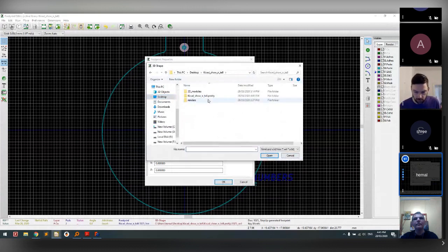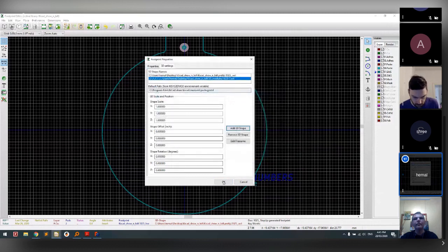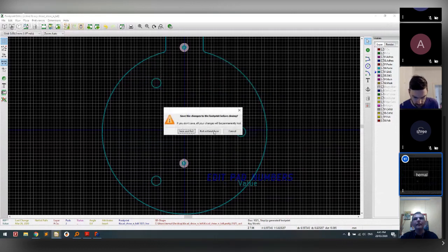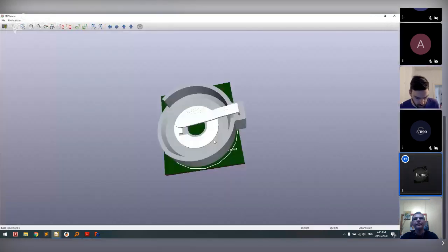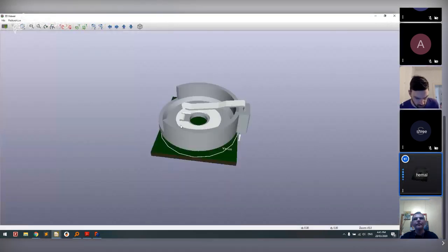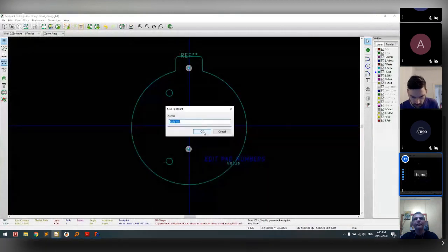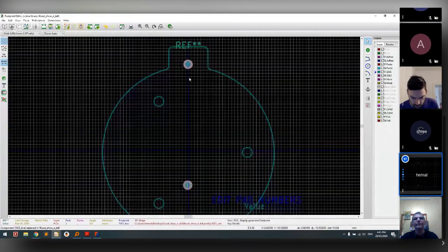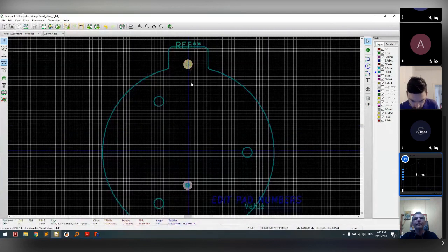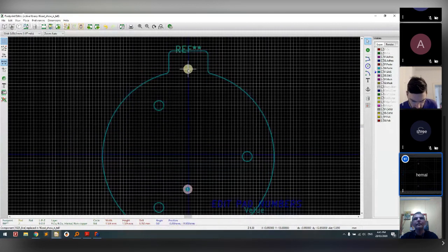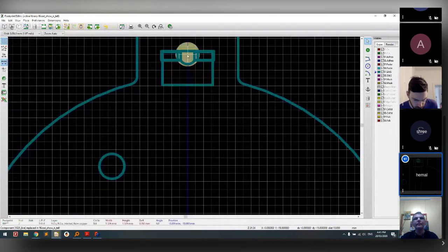This one I think won't be aligned because we haven't used... sorry, yeah, this one is not aligned. Once this footprint is created, let's say this is the footprint, since I've added the pads, they're not in the right location. Let me just bring things back and put it in the ballpark.